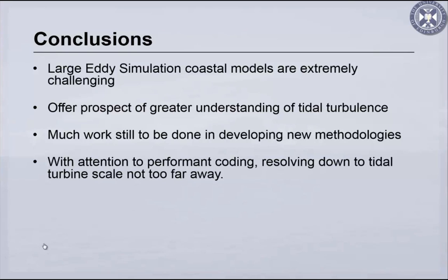So in conclusion, large eddy simulations are really difficult. I'm hoping in 5-10 years' time I can just run this on a desktop and it takes 5 minutes. It doesn't at the moment. It does offer a prospect of great understanding of tidal turbulence, because we get lots of information out about the size of eddies, the frequency of their occurrence, the vertical structure, and we got lots of transient data out of it. Much work still needs to be done on developing new methodologies.